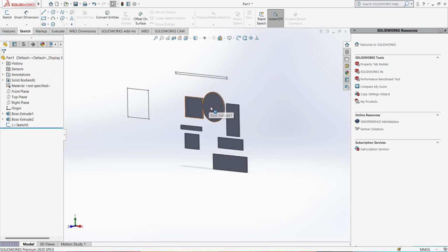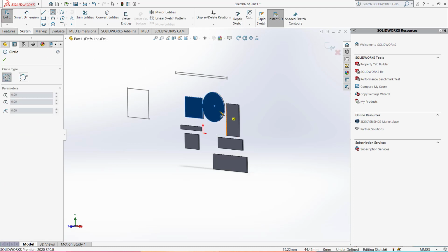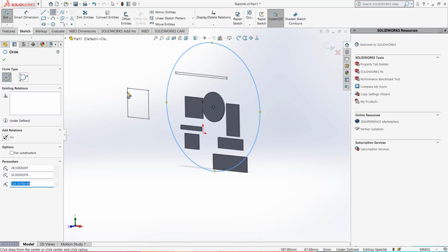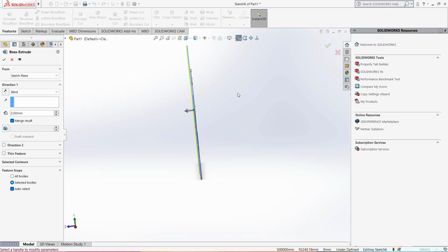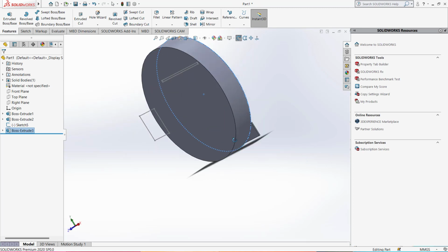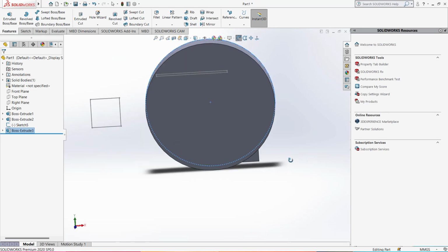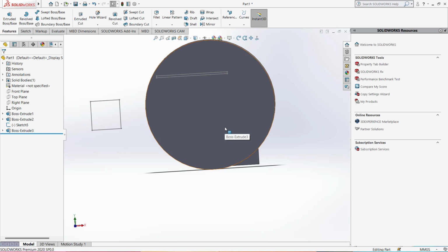Okay. Now, if I want to sketch on this surface, I'd have to choose that surface and then hit sketch. Then I can come ahead and then use that surface. So in that case, whatever I do is only appearing on that surface and nowhere else. Okay, great, like you can see. So as long as you choose a specific plane or a specific surface for your sketch, SolidWorks is never going to give you the option to sketch anywhere else.